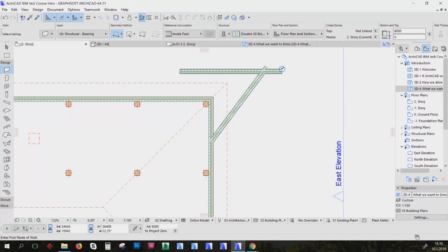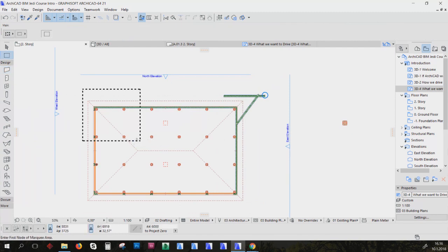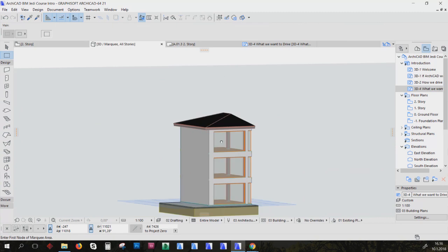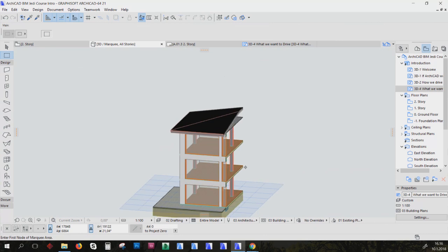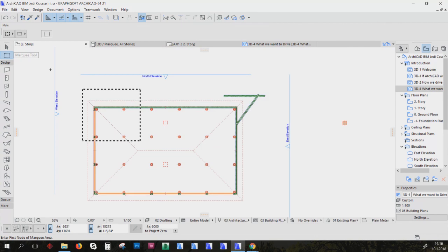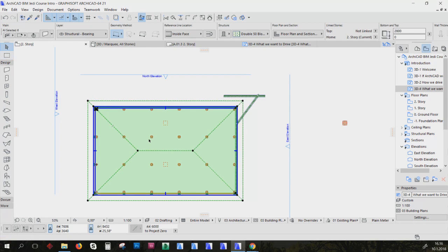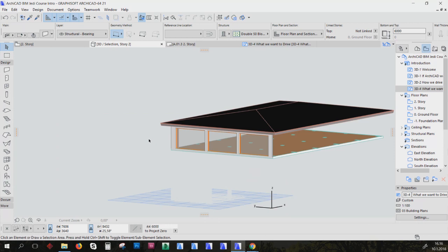What else? Next one is, if we wanted to just grab an area and have a look in 3D, it's generally just F5, and as you say, this keyboard's got a function, so it will take just the part that we've selected and show it. That works the same if you've just selected some objects, not a marquee. F5 will show you those selected objects.